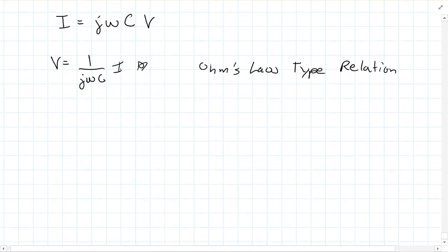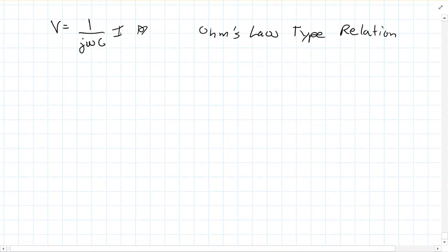And now, we're essentially done today, but I want to emphasize what are the three equations we really learned today. Well, these are all phasors, remember. So V is equal to IR, it's still the same. Then for an inductor, it's V is equal to j omega L times my current.